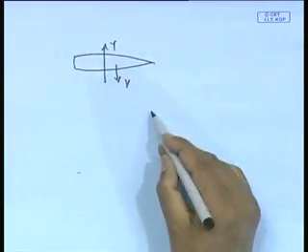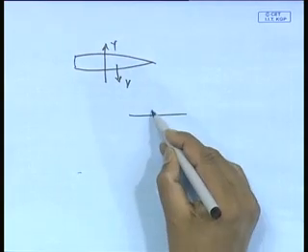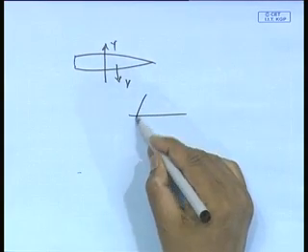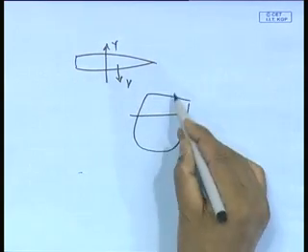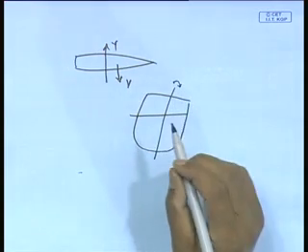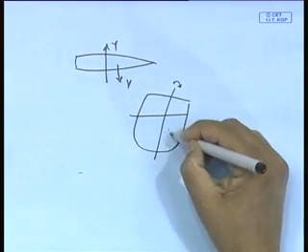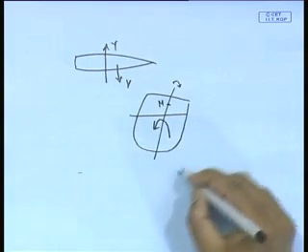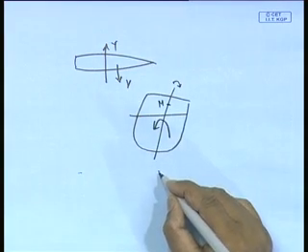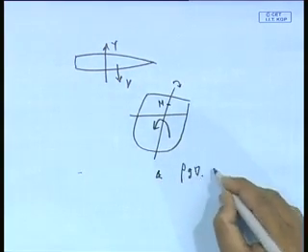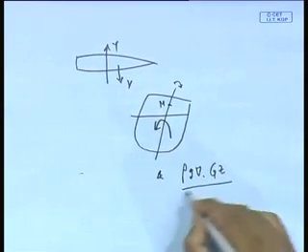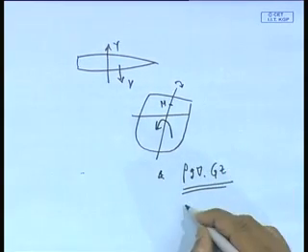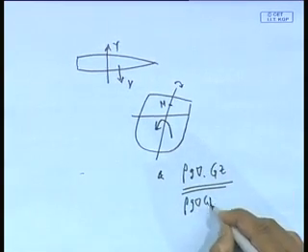Now, look at this, our example with a heel motion. If I were to heel it by an external source, what happened? A static force comes if the metacentric height is high. I end up getting a delta, or I like to write it this way, writing the moment this way, or I can call it delta, G M into theta.